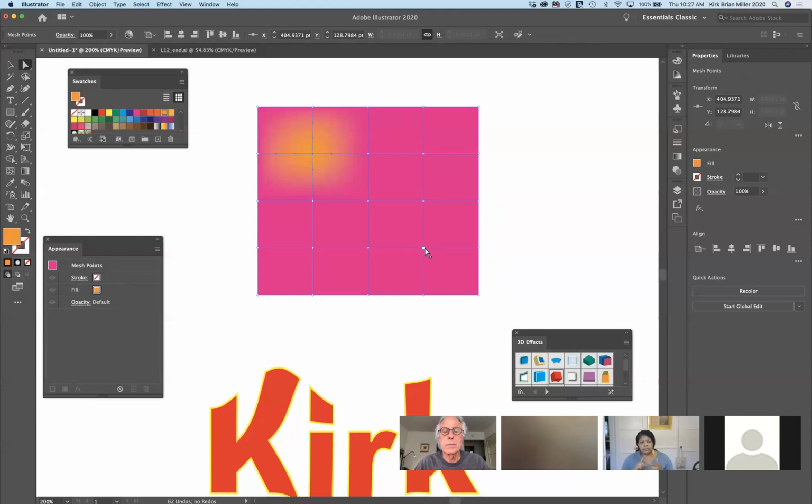But now with the freeform gradient tool, it kind of makes this silly and unnecessary, because in order to move these, you have to click and drag, and you can also twist these little handles. But this was how you would create realistic gradients in the past for modeling form prior to the freeform gradient tool.